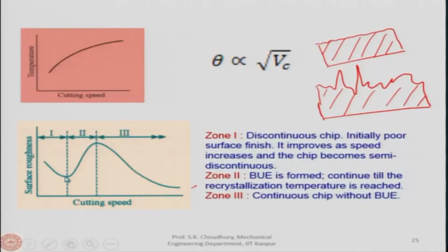If it is a mild steel curve, in that case this will be the 80 to 110 meter per minute cutting speed, and then since the built up edge forms, the surface finish will be bad, because again the cutting force fluctuates, then the power fluctuates, as I said, the rake angle changes, and it is a dynamic change in the rake angle as the built up edge piles up and then it breaks.